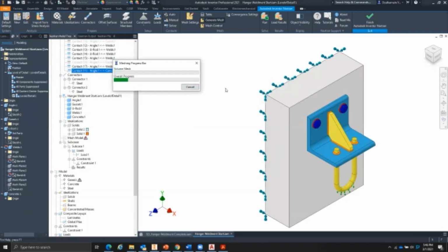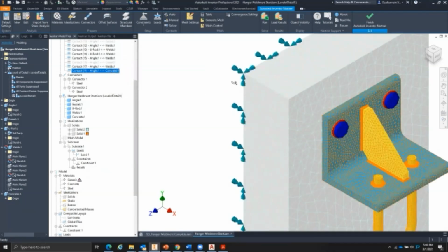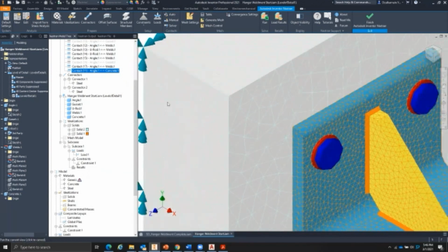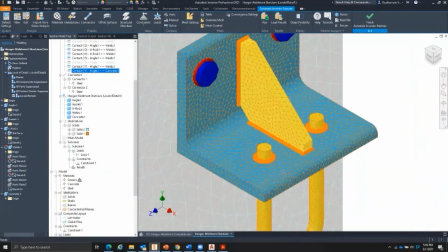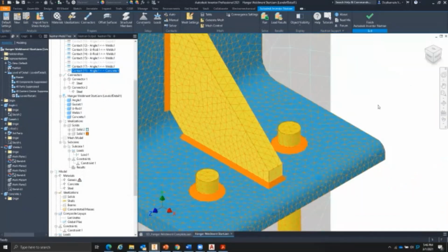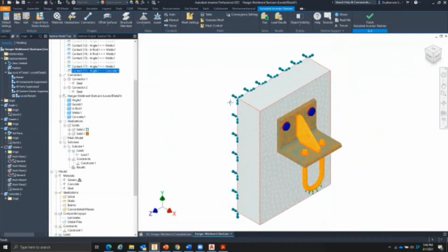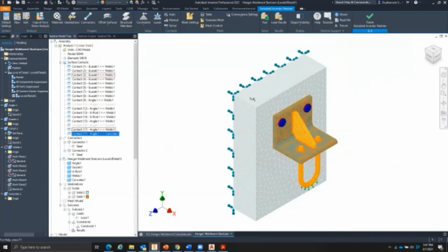So let me just click generate mesh now. So we'll see how the mesh looks like. Okay, so remember that I put 15 for concrete. So you can see that the concrete here is bigger. Okay, and then 2 at the well. So you can see at the well it is smaller. So the rest is 4. All right. So now, after checking, everything looks okay now.